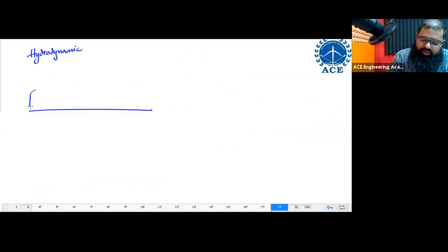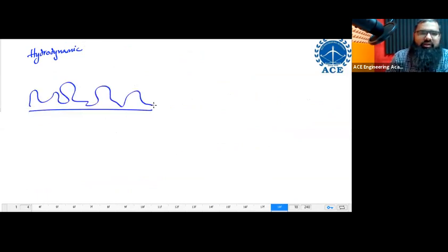Look over here. Imagine you're having a particular pipe with some roughness. Some big pipe is there at the wall. I'm having this cross-sectional view. I bring you the pipe and I ask you, tell me whether it is a smooth surface or a rough surface. What should you answer? Your answer should be data is insufficient, or I don't know right now. Why? The reason is roughness or smoothness of a pipe is not just based on epsilon. When I give you a pipe, the only thing you know right now is the value of epsilon, nothing else.